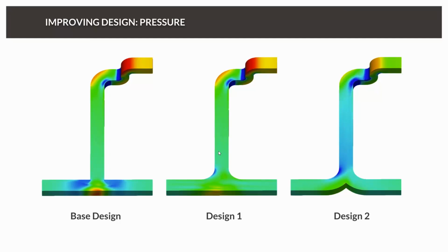and this results in this big pressure drop on the left and right side. Adding the radius helps a little bit, but it leads to a new kind of flow separation on one side of the junction, and we still have the stagnation of the flow at the back wall, which can also be seen in the high pressure area near the inlet.